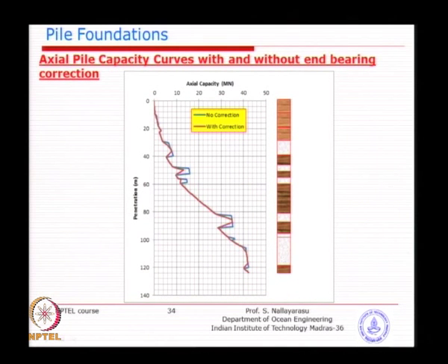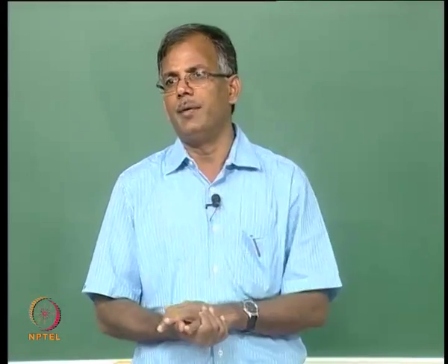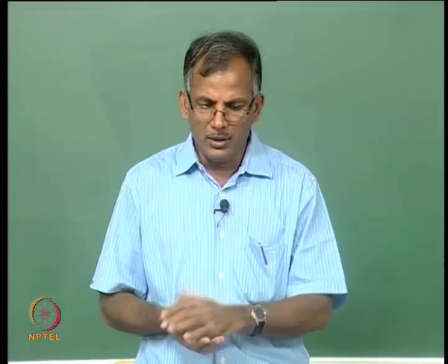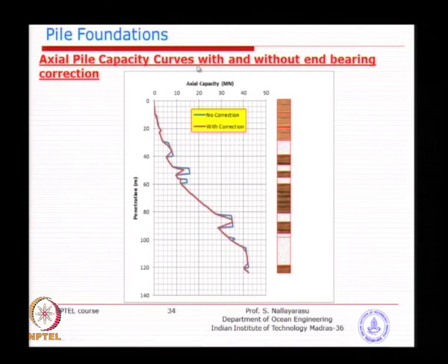We will now look at capacity generation for interface layers. For example, if I have only a single layer of soil, clay or sand, then there is no issue. Whereas, when you are talking about offshore pile systems, you see here multiple layers of alternating types, sand and clay. You can see here predominantly clay material, except at several locations at intermediate depths of sand material. Now, you see here this is a slightly deeper sand layer, and then you have a slightly bigger layer.